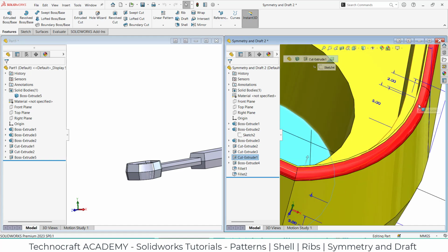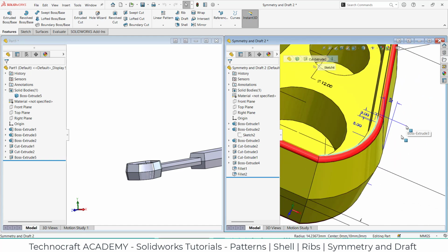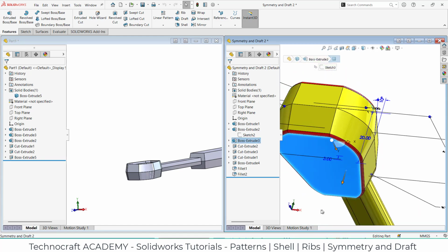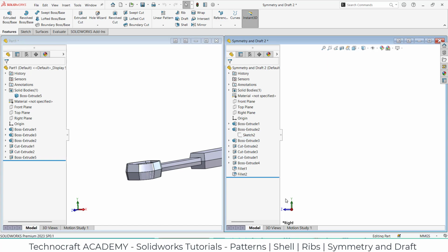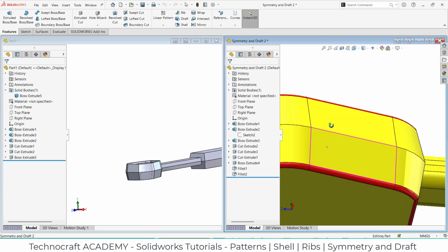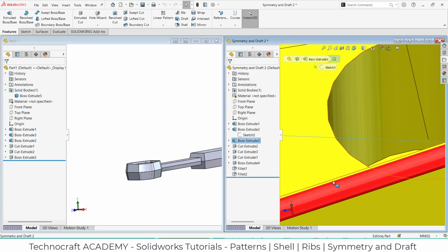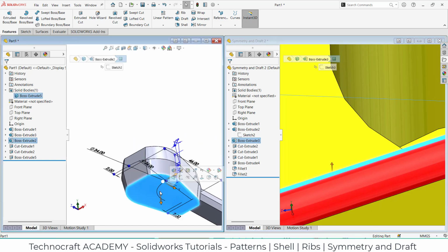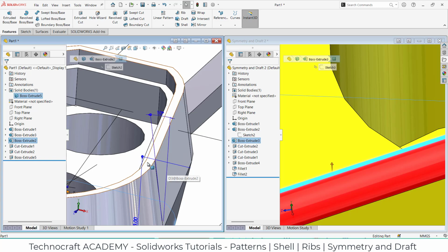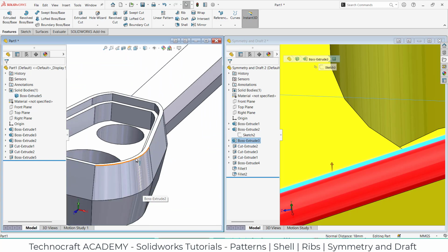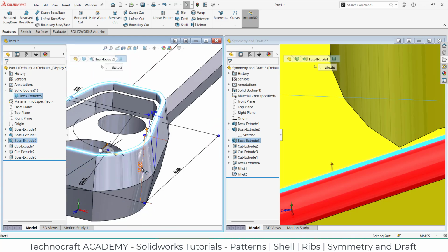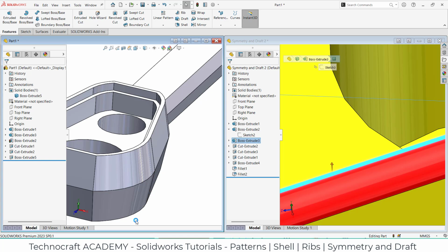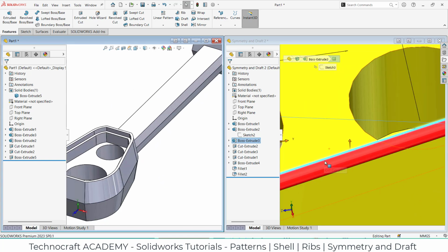So from this face, just for our confirmation, it is showing from this face to this flat face, this 20. For me also it should be 20, or it is 18 here, so I should increase it now. So what you can do is you can just select this face and double click on this and make it 20. Yeah, control B. Yeah, so now we are almost done.